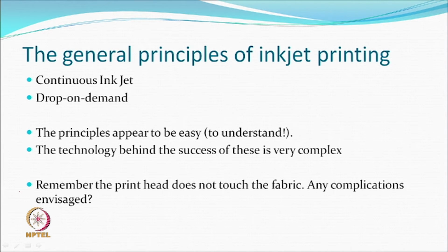That is the reason for pre-treatment, not the bleaching and covering we were talking about, but pre-treatment so the surface becomes a little more smooth, so that nothing touches, because it can wrinkle, it can get skewed, all those things happen with tension, which does not happen in paper. Paper is a much more rigid body, whereas textile is a flexible material, and therefore this is important. Of course, it was always important in printing to make sure the fabric does not slip.